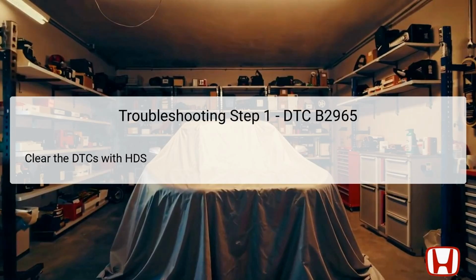The first troubleshooting step in addressing DTC B2965 is to clear any current diagnostic trouble codes using the Honda Diagnostic System, HDS. HDS is a specialized tool used for diagnosing and troubleshooting Honda vehicles. It provides a means to reset the vehicle's computer system after codes have been noted and before further diagnostics.